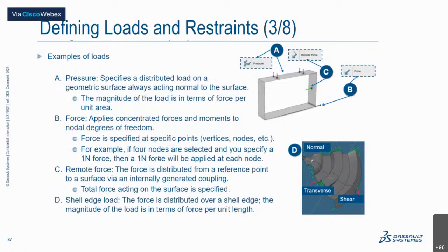Now, we'll be talking a little bit more about the remote forces, but for now, the shell edge load. So shell edge load is basically force per unit length. It distributes the force load over the shell edge. So these are for shell components where you can use this particular shell edge load command.